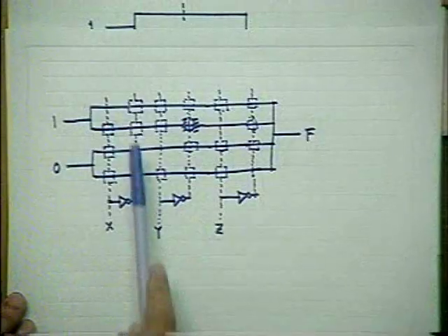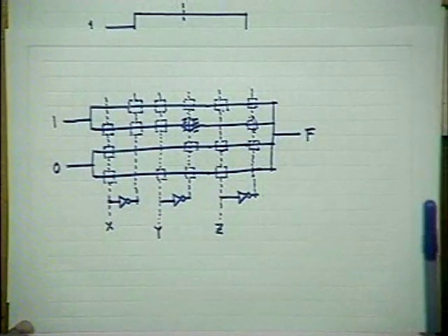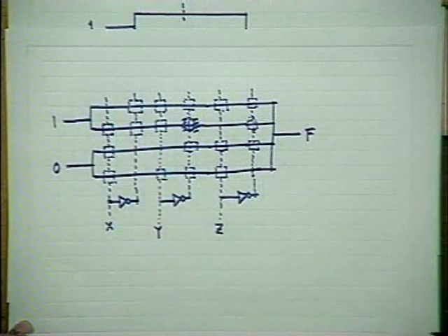Yes, there will be unnecessary signal delay and there will be delay inequalization. Delay here and delay here will be different. So ultimately there may be problems if this is an asynchronous logic. But even in synchronous logic, you have to use a much lower clock frequency. You have to wait sufficiently so that things stabilize. Okay? So this is the problem if you use all the inputs like this, because you see that here the poly lines will travel from one end of the chip to the other end of the chip. So this is a drawback. Can you suggest something to get rid of it?